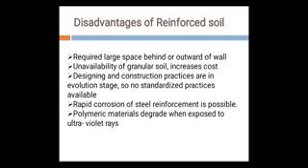Now there are some limitations or disadvantages. A large space is required behind or outward of the wall. So there is a large space requirement while constructing this reinforced soil. Unavailability of granular soil increases the cost.